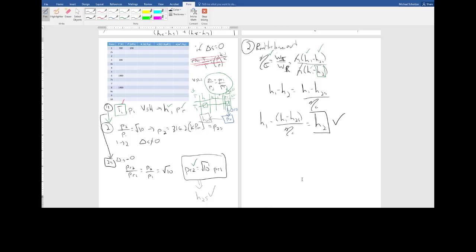And then I said, as I go from state 1 to 2, where is the isentropic process? It's actually not state 1 to state 2, it's state 1 to state 2S. And then I used my isentropic relationship to fix state 2S because I knew the compressor pressure ratio. And once I knew state 2S, I could use the compressor efficiency to find state 2.